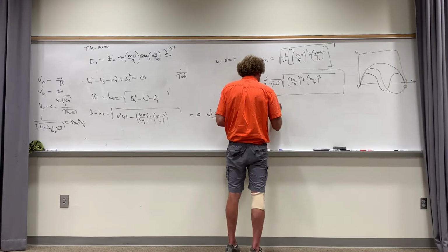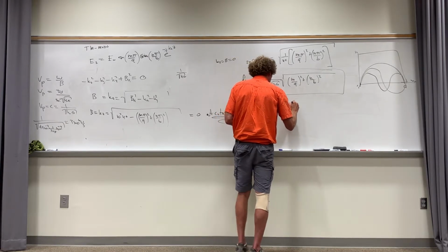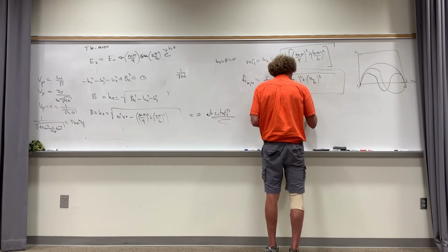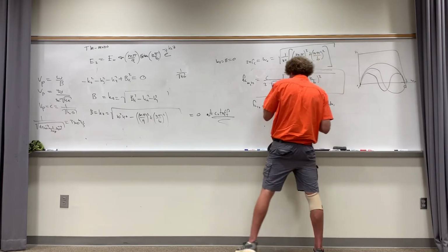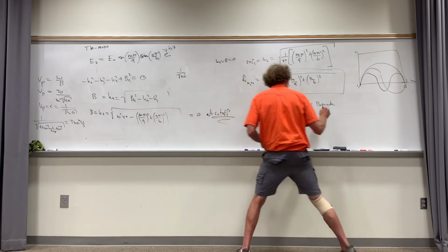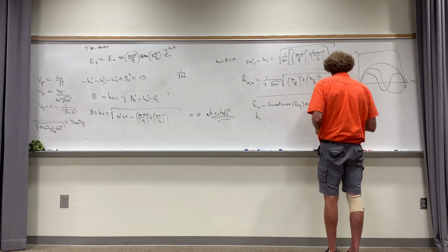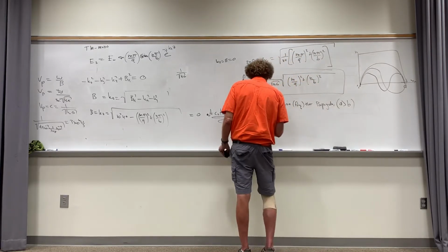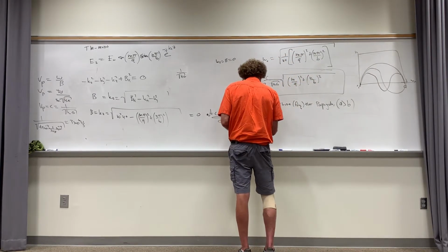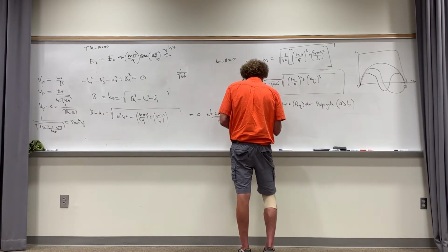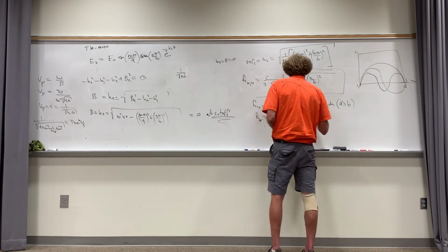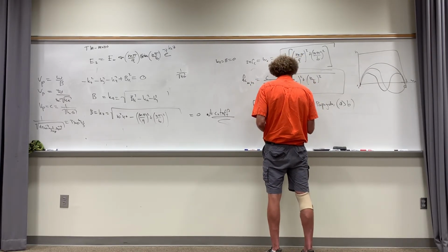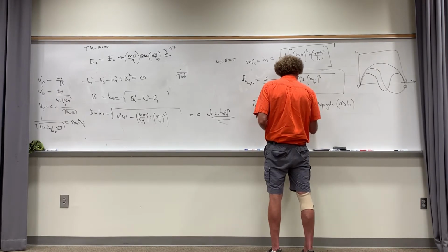FC10 is the lowest mode, or lowest frequency, that propagates. That would be FC, assuming that A is greater than B. If it's the opposite, then it's the 01 mode. FC10 would be equal to C over 2 times the square root of mu relative epsilon relative times the square root of, you can forget about N, it's 0, it would just be 1 over A squared.